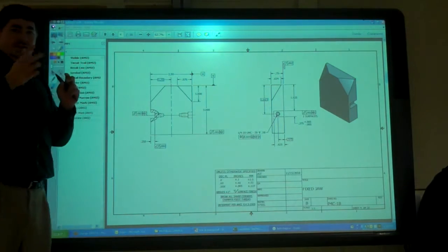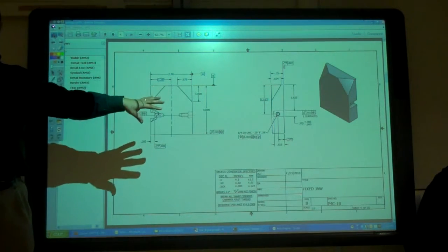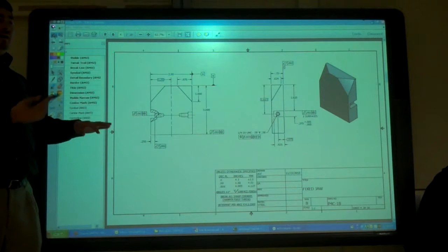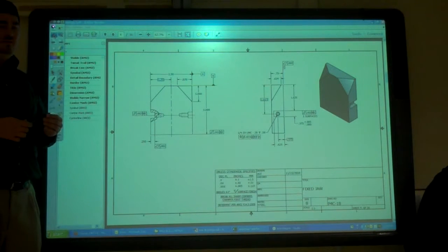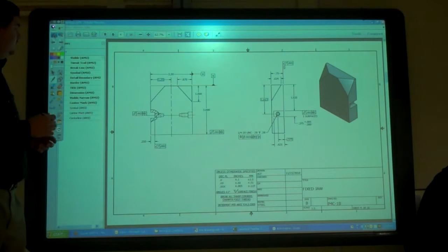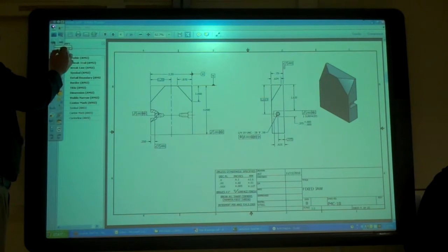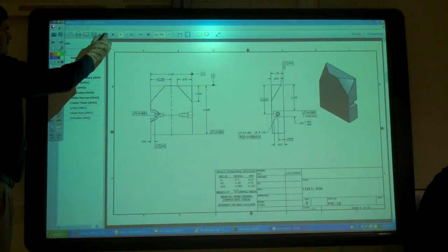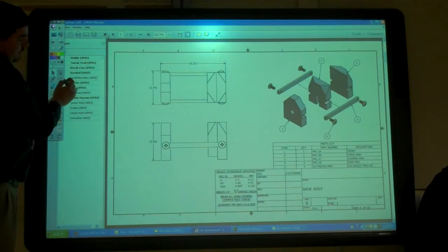Okay, is this easier to make? Then they might see that and go, okay, let's do an engineering change request, send it back to engineering and see if they can change it. Yeah. Making those corners though, depending on what your clearance tolerances are, if you have pretty big tolerances, it doesn't have to exactly be a corner. But this is pretty tight.